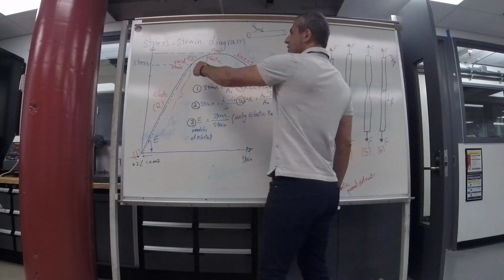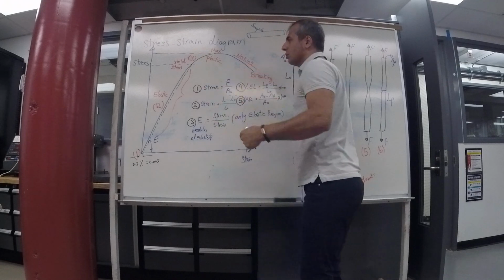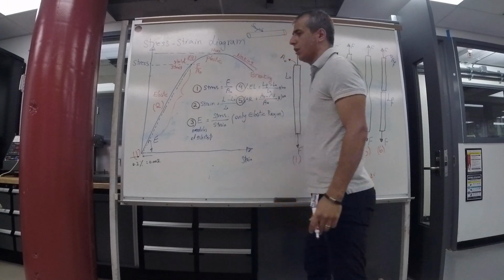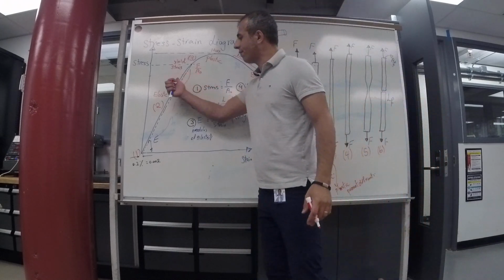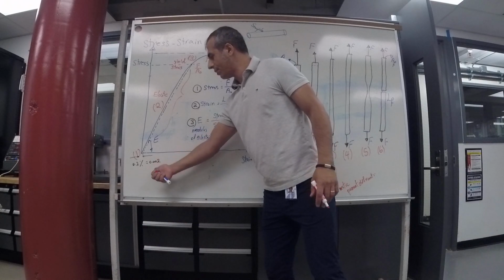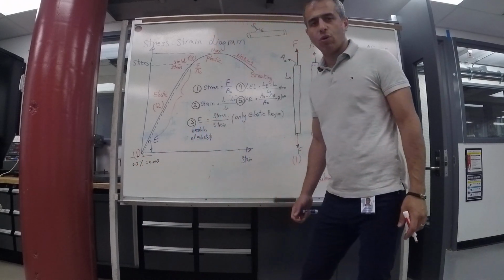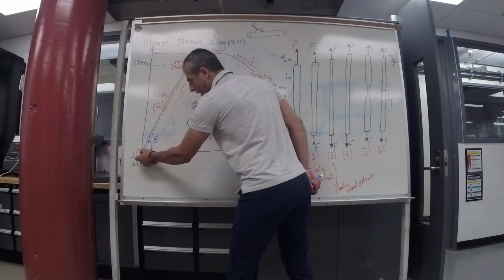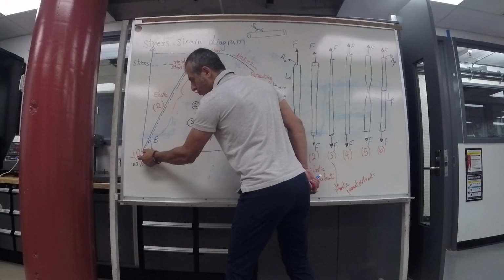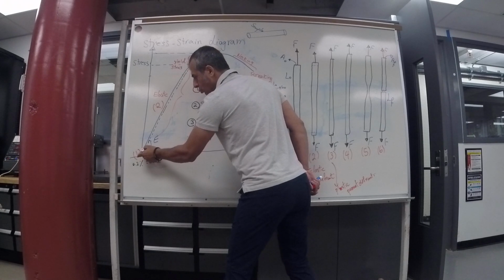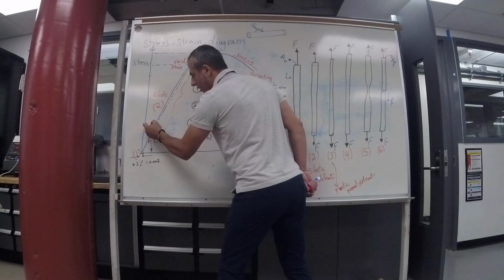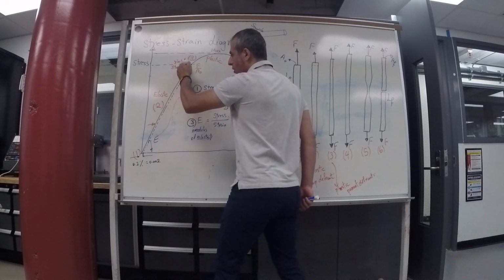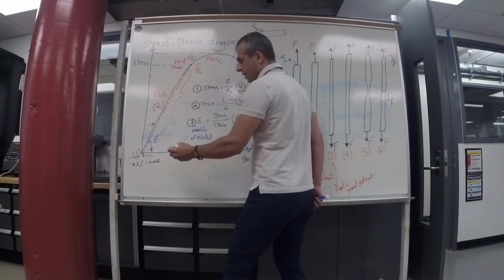How can we find the yield point here? Simply, yield stress is the force at this point divided by the original cross-section area. But if you have a graph, we have a technique named 0.2% offset from origin. 0.2% means 0.002. We scale that to 0.002, put a mark here, then make a dashed line parallel to the elastic line, because the elastic part is linear.